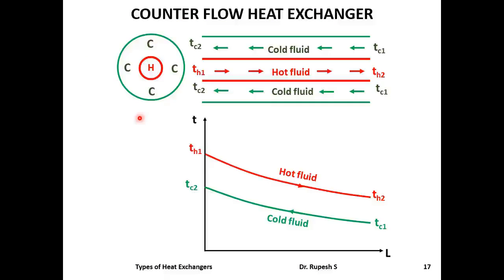We have seen that in a parallel flow heat exchanger, both hot and cold fluids move in the same direction within the heat exchanger. Whereas in a counterflow heat exchanger, hot fluid and cold fluid move in opposite directions. This is also clear from the temperature profile. Here hot fluid is dropping its temperature in this direction, whereas cold fluid is gaining temperature in this particular direction.